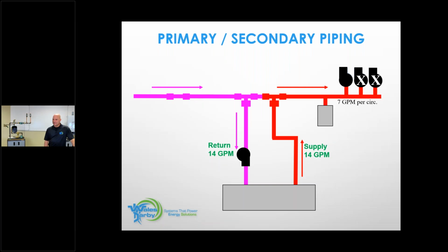We have a high achiever here today. Yeah? What do we got? He nailed it. Okay, good. So he took 20-degree delta T, multiplied that by 500, equals 10,000. 10,000 times 14 equals a 140,000 BTU boiler. So that's what we currently have here.